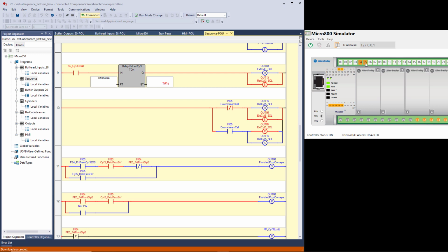Okay? It starts running, and the part is still in front of that sensor that's input 4 right here, photo eye 5. It's still there, but the conveyor is pulling it out of that photo eye. So let's turn off input 4, and you see that the conveyor keeps running. That's because we need that conveyor to run that part all the way out of the system. But we don't want to leave that conveyor running forever.